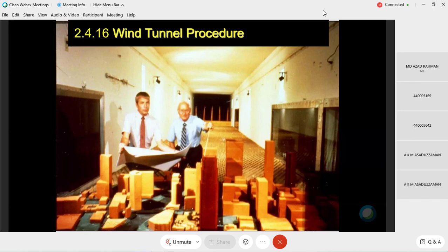In London was Alan Davenport. Now there is a major one in Guelph, Ontario, that's totally private. Anyway, so this is typical wind tunnel testing. You simulate the roughness of the ground here by putting different kinds of carpets and things. These are models of the buildings, not only the building that you're designing, but also neighboring buildings, because the neighboring buildings will have an effect on your building.